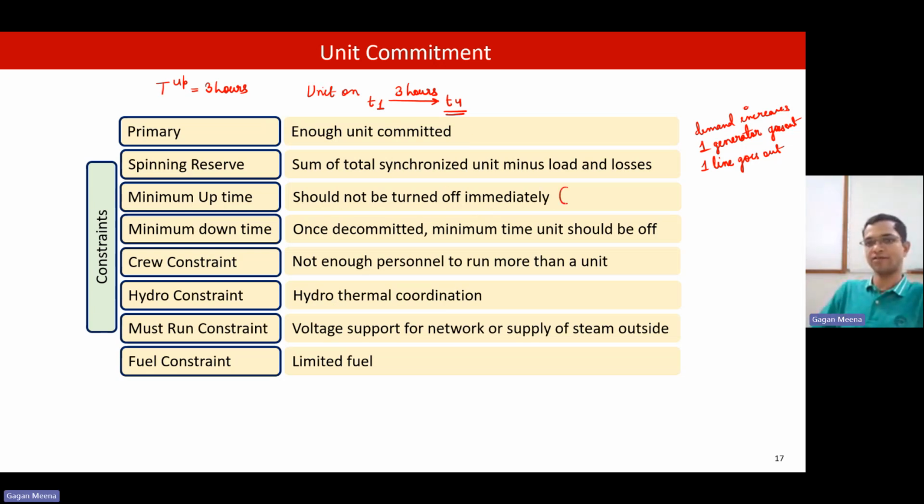It should turn off only after the minimum hours of being on. Similarly, for downtime, if a unit is decommitted, if it is off, it should remain off